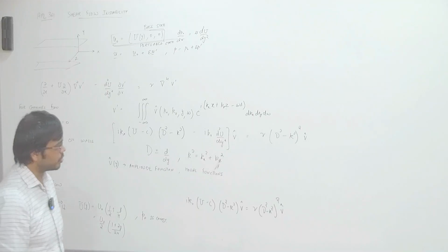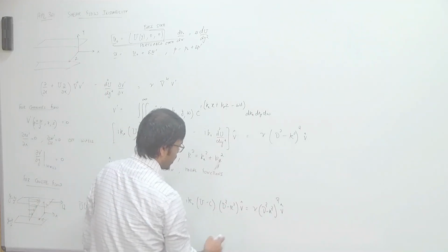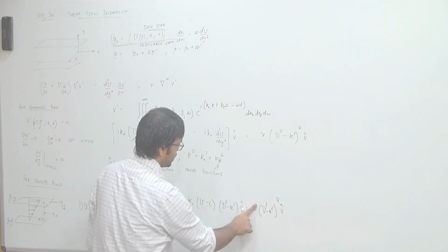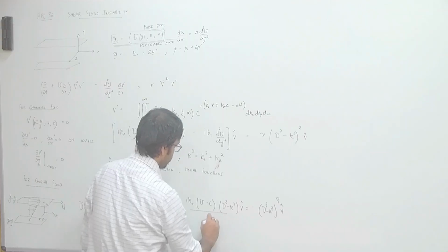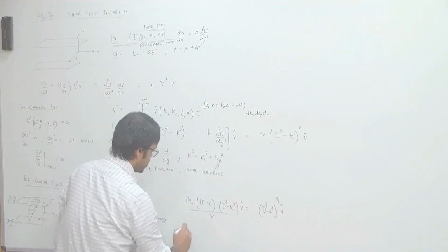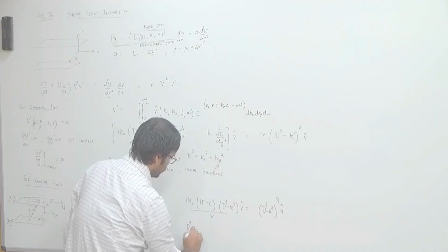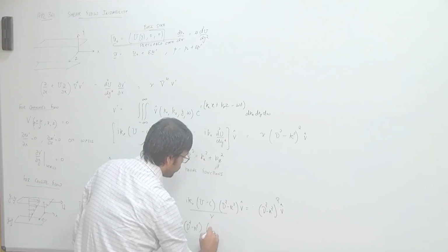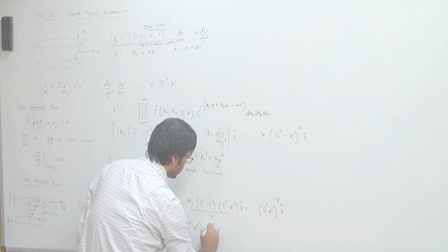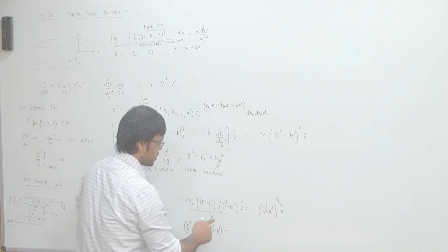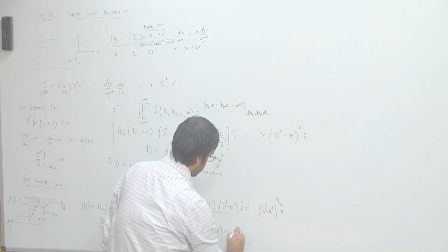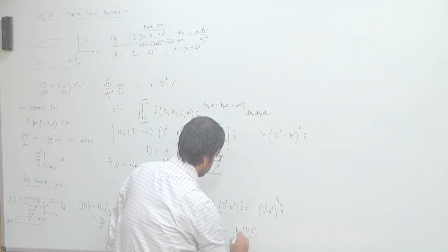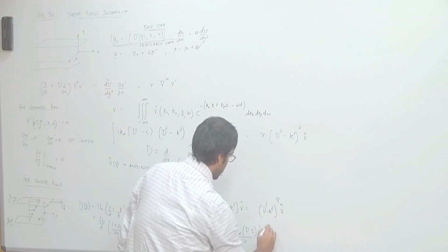Okay. So, you can rearrange this equation and then, let's divide this LHS by nu, and let us look at this equation. So, you can write (d2 minus k square) of (d2 minus k square) minus this whole thing, i k x (capital U minus c) over nu, times V hat equals 0.